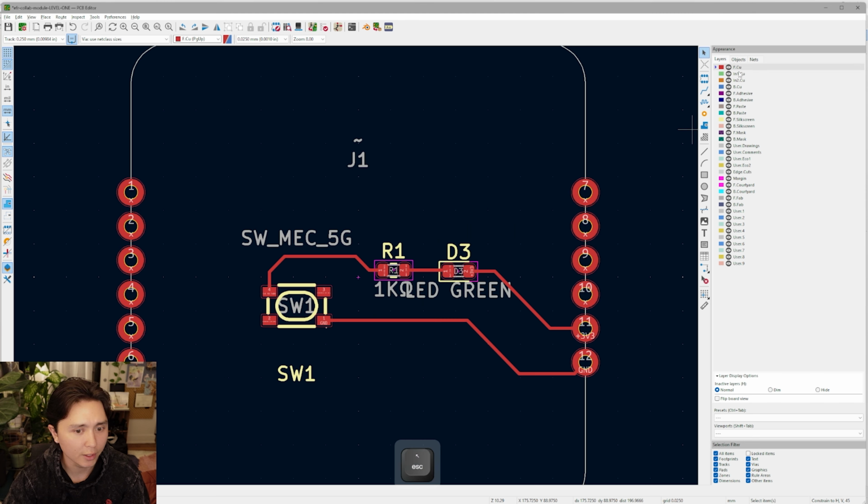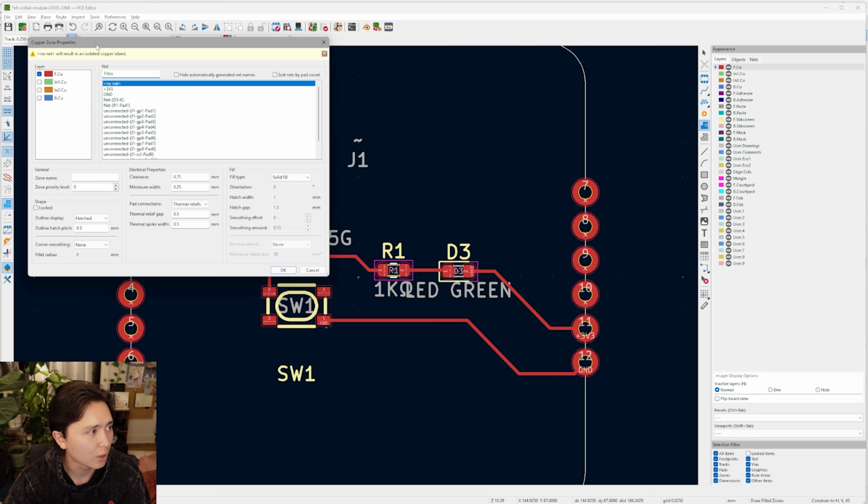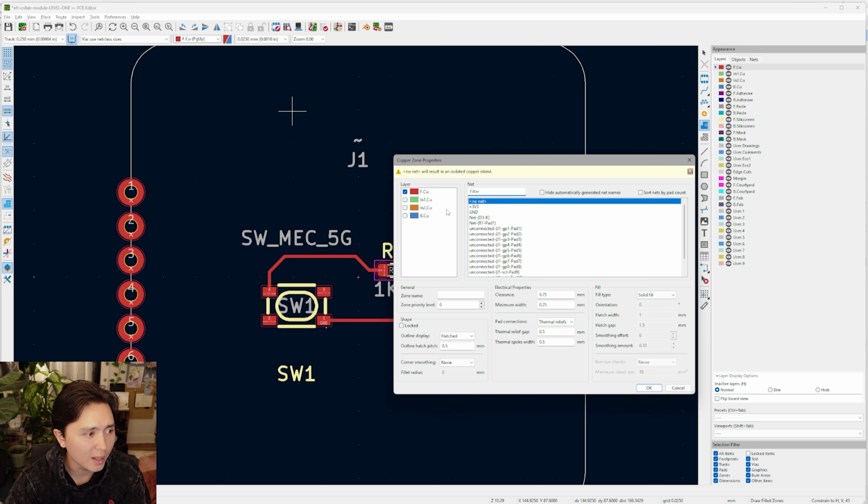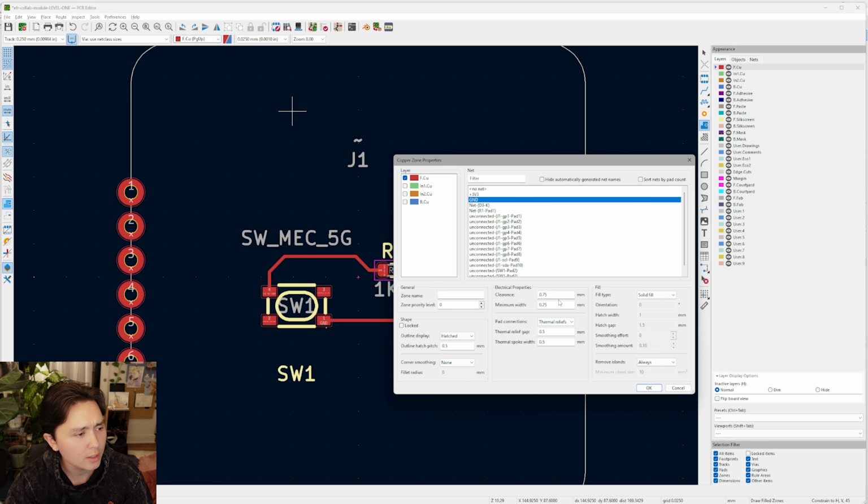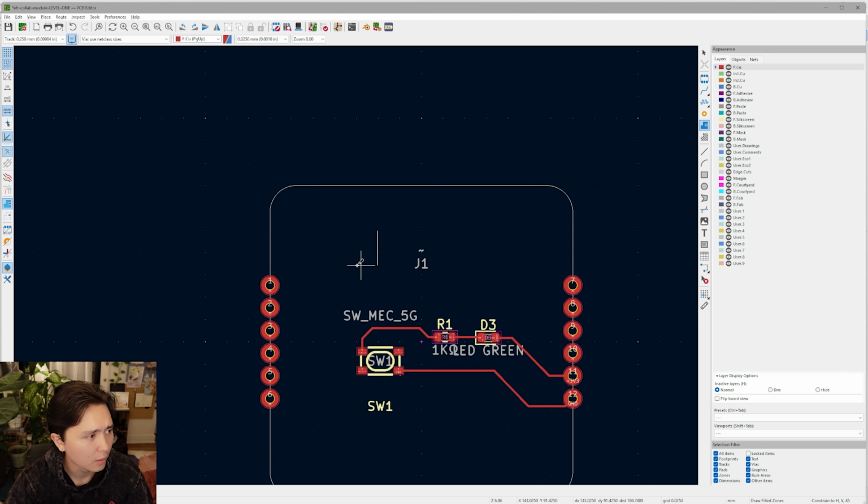We'll go back to our copper layer, the front copper layer, and we will choose draw filled zones. And I will just start clicking. It'll immediately ask me, hey, what is this copper supposed to be connected to? Like you're basically making a new pad, and I need to know where it goes. So let's make it a ground, okay?